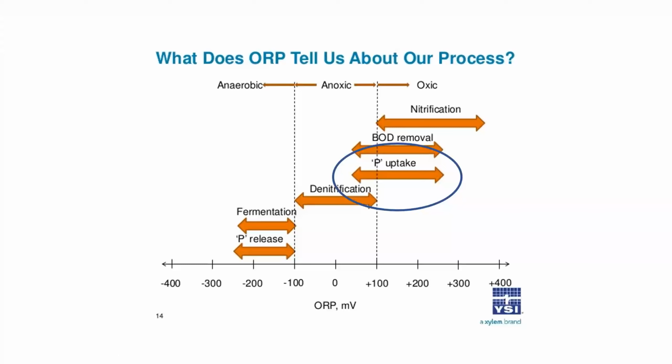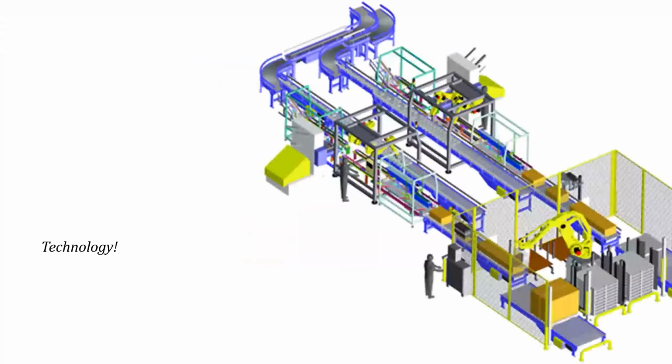Fantastic test. You do a daily measure of your effluent ammonia, and if it's low, then as long as that pH is 6.8 or higher, your aeration basin is good for phosphorus removal. A little asterisk there: as long as there's enough BOD to drive it, which I'm kicking down the road a little bit here.